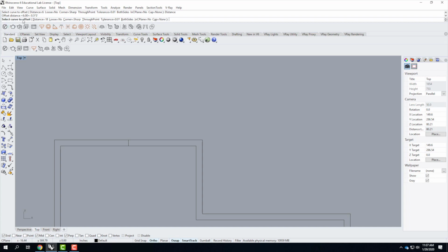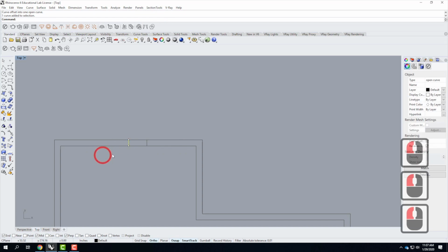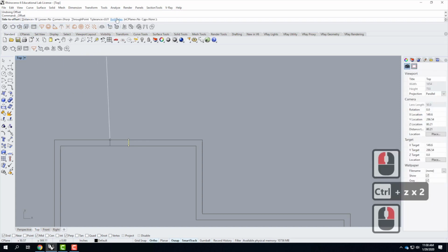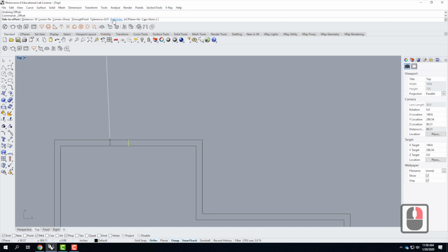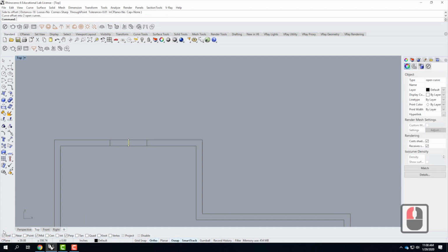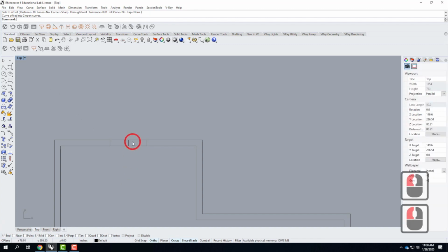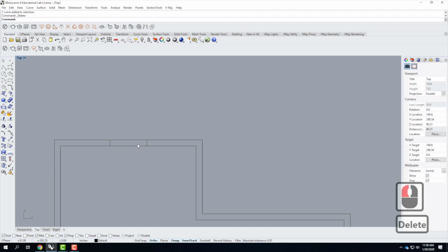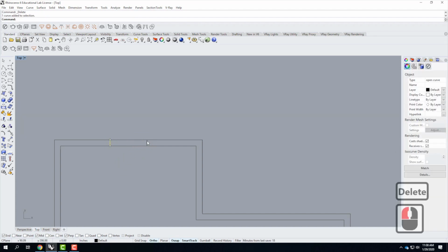That's what I wanted. Now, I could pick the curve and go one way, and pick the curve, and repeat the command and go the other way. But Rhino also has the ability, when I'm doing the offset here, to select right here both sides. So if I type B followed by enter or click on both sides, it will do the offset in both directions at once. So it saves me a step. It's kind of nice. So I can go ahead and do that. It gives me both sides. At this point, I can also go ahead and delete that original line because I don't need that anymore. So I'll press the delete key. So I have this side and I have that side.